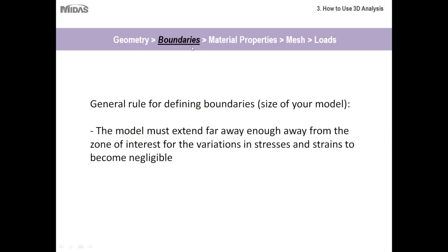Now we'll go into boundaries, or creating the size of your project. The main rule to keep in mind is that the model must extend far enough away from the zone of interest for the variations in stresses and strains to become negligible. In other words, your model has to be big enough so that the stresses and strains from the point of interest become negligible as you go farther and farther away from it.